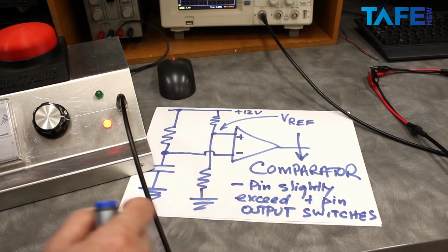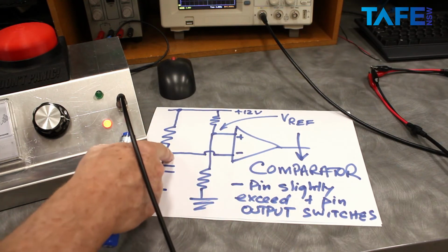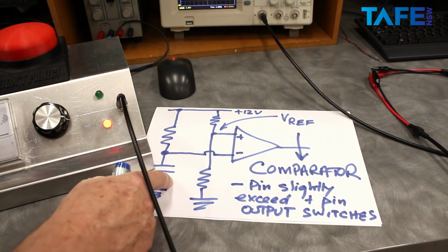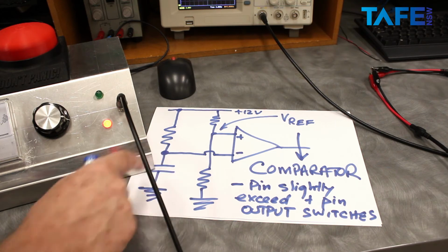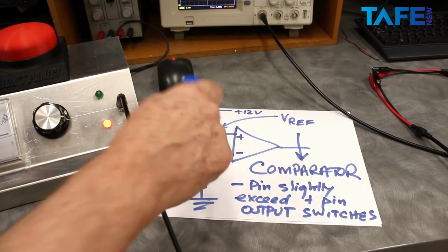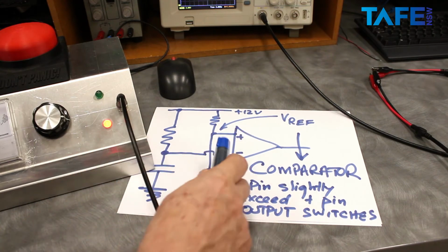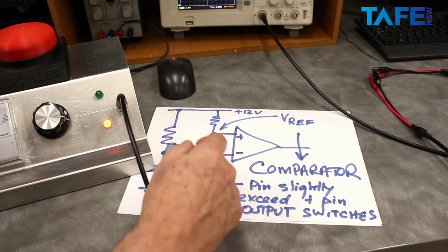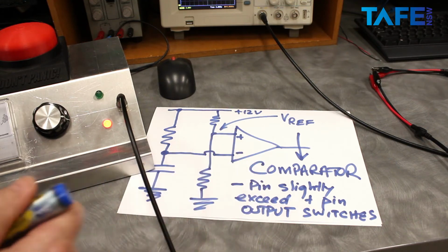So where we saw in the last segment that we do not want under any circumstances a resistance across this, which is going to load the circuit down and form a voltage divider between here and ground, this is ideal because that large resistance, probably more than 1 million ohms, won't affect our circuit too much.